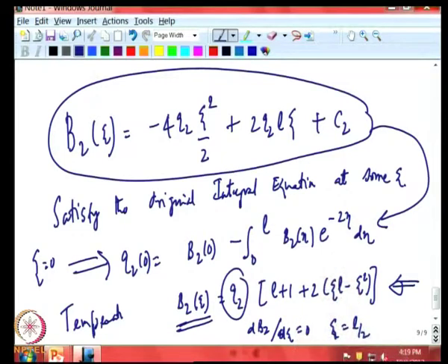So, these are very useful results that you obtain analytically, which can be used to tune your code, because when you solve the problem numerically, you have to make various judgments. You have to decide if you want to divide the tube into 100 parts or 1000 parts before you do matrix inversion. Now, that really depends upon what kind of accuracy you want to attain. So, the accuracy goal has to be stated clearly, and once you state your accuracy goal, then you can decide. Suppose you want either radiosity or temperature accurate to 1%, then that will determine how finely you want to divide the tube into many parts.